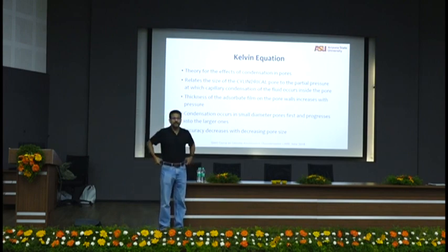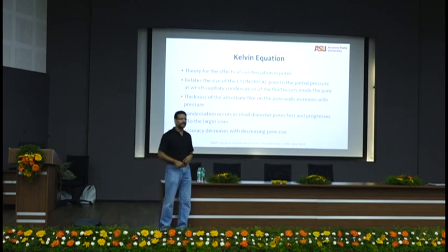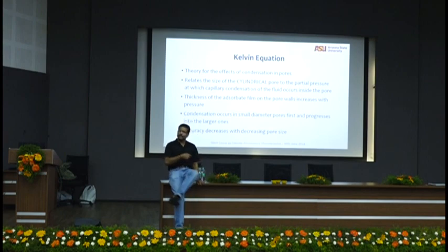BET instruments should be available in many material characterization labs. Anybody who deals with any kind of powder uses this method for specific surface area. So you can hydrate a cement paste. You can just powder it nicely, give it to them. You can find the specific surface area, and you will know that you put in 25% fly ash, you put in 30% fly ash, you put in 50% fly ash, very quickly you will find out how much fly ash is there in the system.